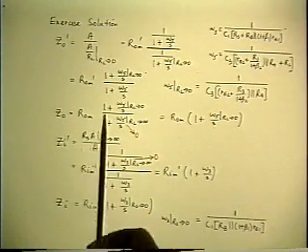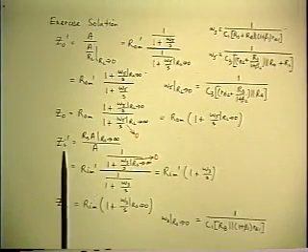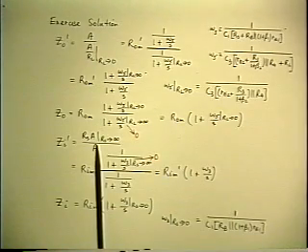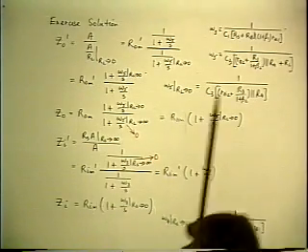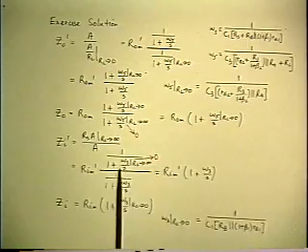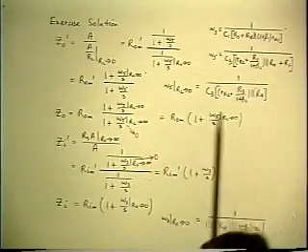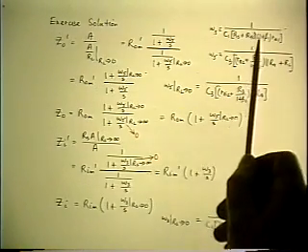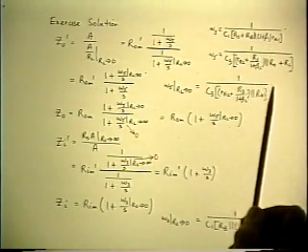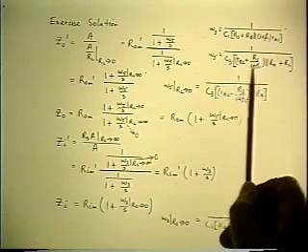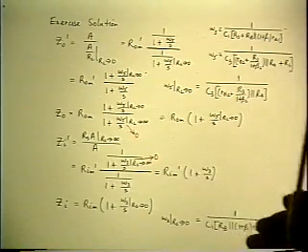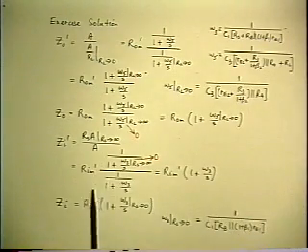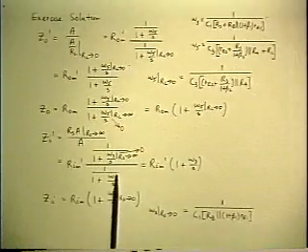To find the input impedance, you simply apply the formula to the appropriate gain, which now also includes the omega-3 and the omega-5 inverted poles. The mid-band value you don't have to do again. You look at the poles and see where the RS is. This time the RS is absent from the omega-5, so the entire factor cancels, and I haven't shown that before either.